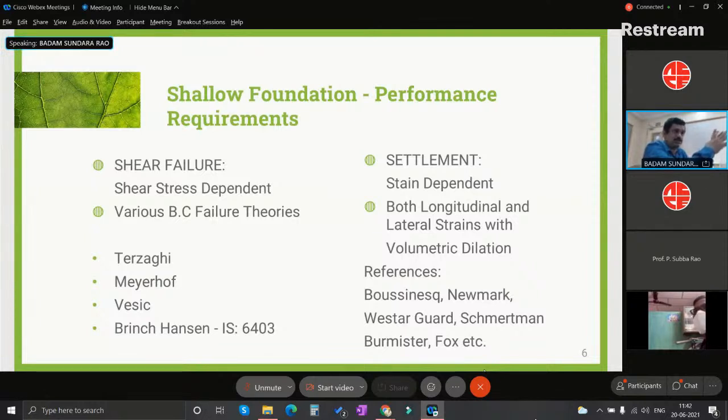Regarding the way bearing capacity is considered, this is one of the practical applications, especially for Kakinada also. We have bearing capacity factors for the punching shear failure, that especially pertain to a layered soil system where there is a strong soil underlain by a weak soil. Kakinada typical profiles are like that, with top layer sands followed by soft layers. These are two-layered soil systems. For the two-layered soil system, Meyerhof proposed a punching shear failure criterion, and also suggested the punching shear coefficients, which are highly helpful for the design of any foundation system. And Vesic's method is again 1963 work.